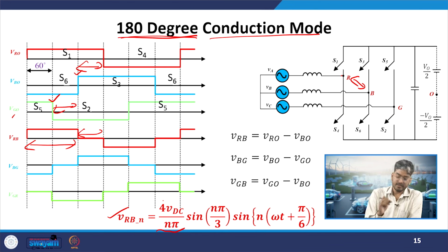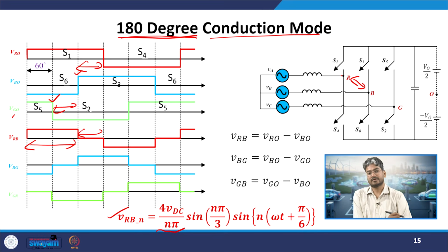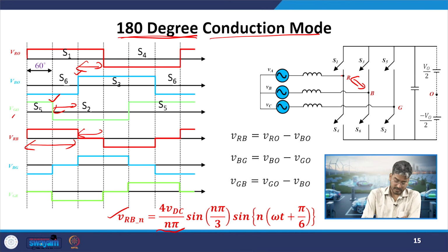It will not have any better performance in terms of your THD, because lower order harmonics are present, or the dominant harmonic is at the lower end. So, the load will be highly stressed. We have discussed what the dominant harmonic means in the last class. Advantage wise, it has fundamental frequency operation. Demerit wise, the voltage regulation is not present and we will not have any performance in terms of THD. THDs will be very high.